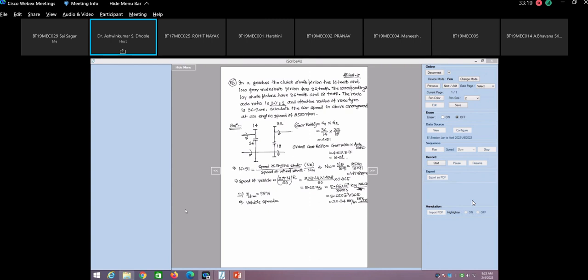सर कितना होगा? मल्टीप्लाइड बाय एफिशिएंसी या डिवाइडेड बाय एफिशिएंसी? 95% का मतलब ये है कि अगर 100 इंजन का आरपीएम रहेगा तो आपको व्हील के पास सिर्फ 95 आरपीएम मिल रहा है. तो इट इज 20.34 मल्टीप्लाइड बाय 0.95. सो इसका वैल्यू कितना आता है सर? 19.32 किलोमीटर पर आवर.